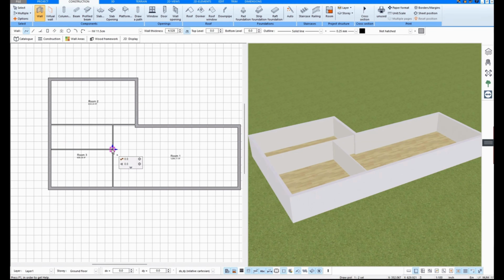I draw as a polygon because I selected polygon here. I now select line, then I draw individual lines. If the wall at the corner is not sitting properly, then press W on the keyboard, and you can align the wall like this.